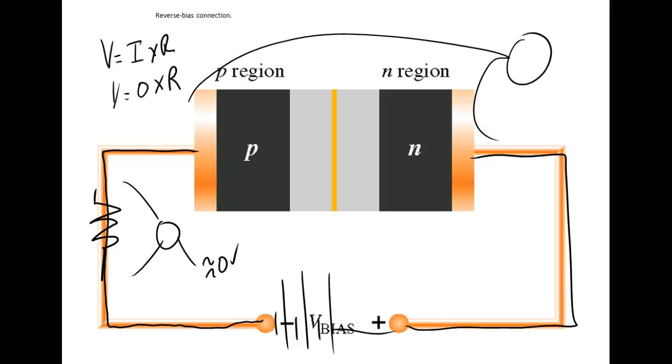So that's why you measure the applied voltage across an open in a series circuit, not in a parallel circuit. In a series circuit, the entire voltage will be across the diode, and then if we forward bias it, we'll get about 0.7 across the diode and about whatever minus that is. Now the 0.7, we'll look at that in a minute. We'll look at different approximations.